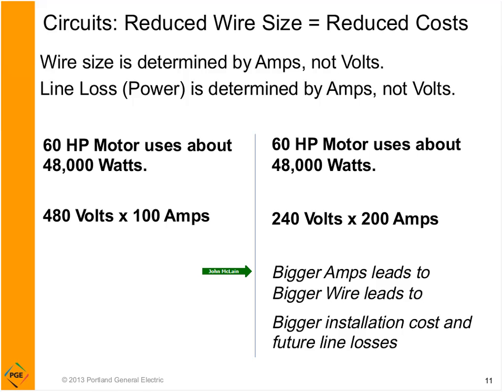The answer then would be, gee, I might want to spend a little money on the 480 volt motor rather than the 240 volt motor because of the installation costs, not because of the monthly bill. In some cases, the panel in this building has a limit. Remember I said 200 amps is residential, it might be 1,000 amps for a commercial application.